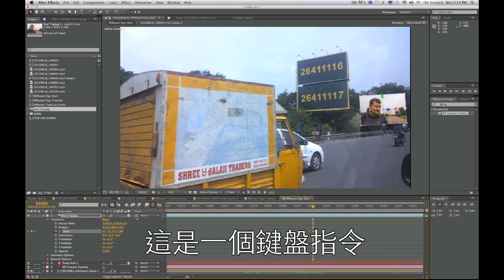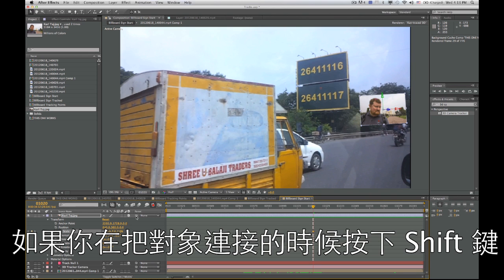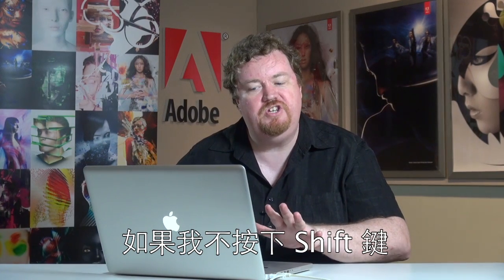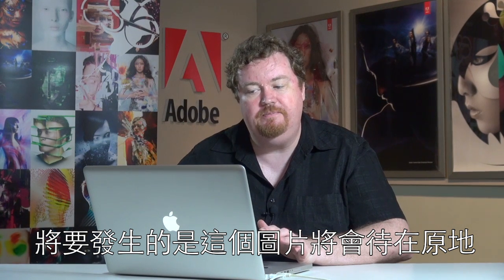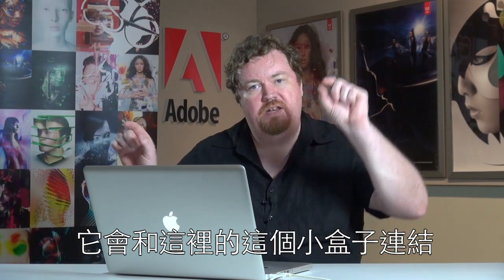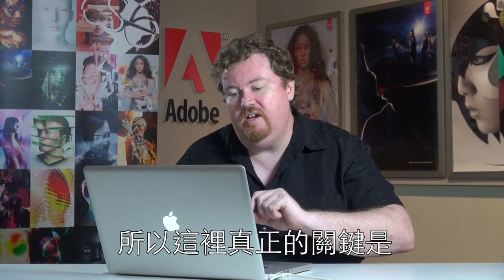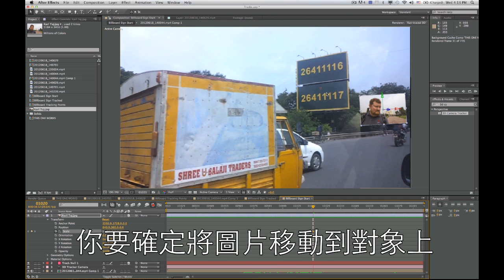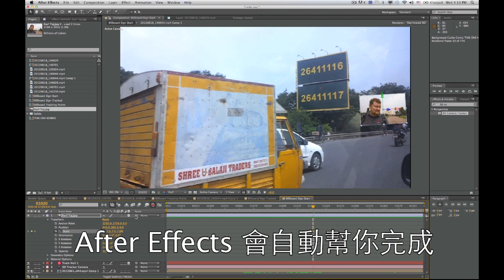Now there's one additional step that we want to do. There's a keyboard command, and this is something to remember if you're going to use this. If I don't hold down the Shift key when I parent an object, the picture is going to stay in its current position, and it's going to be parented to this little box here, but it's not going to be in the same location. So the real key here is you want to make sure and move the picture to that object, and by holding down the Shift key, After Effects will do this for you automatically.